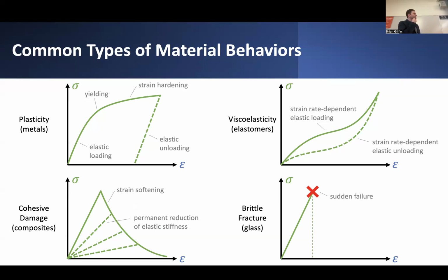I guess I would be a little cautious in distinguishing fatigue as being a mechanism more associated with fracture propagation at a very small micro scale in the material. But in general, it is possible that you can accumulate damage through relatively low or even high cycle loading of the material. So over time, you'll induce small scale damage in the material that could actually result in degradations of stiffness. There are certain cases where maybe you're doing some kind of hysteretic loading loop of some material,